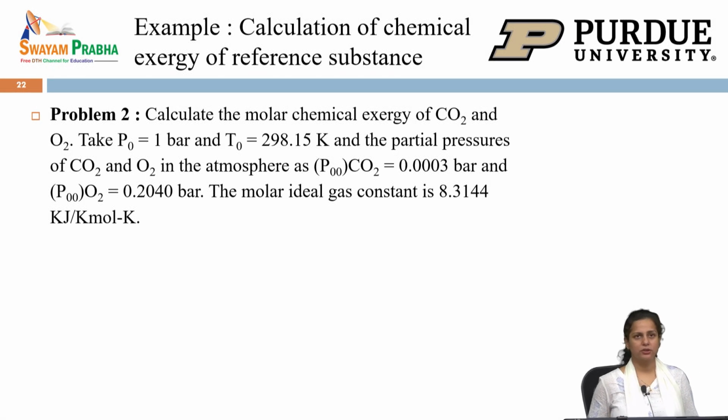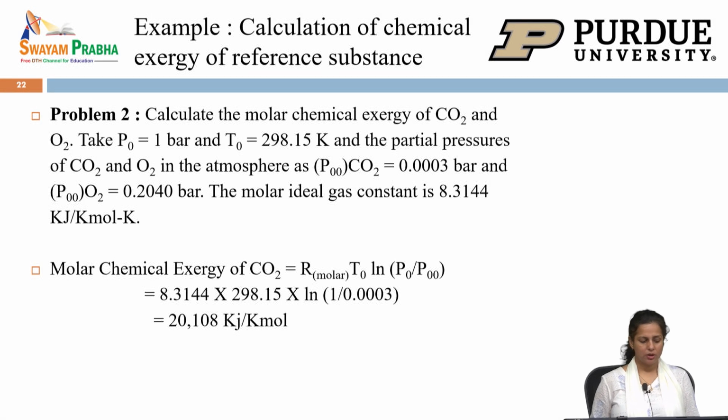So, let us look at the solution now. The molar chemical exergy of CO2: it's a reference substance because it is existing in the atmosphere already. So, we can use CO2 as a reference substance. The pressure is 1 bar for the whole air, but the partial pressure of CO2 is 0.0003 bar.